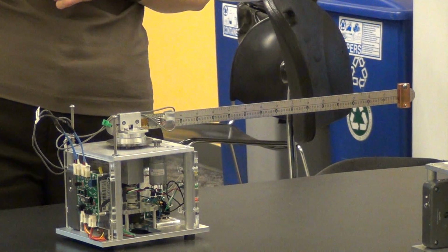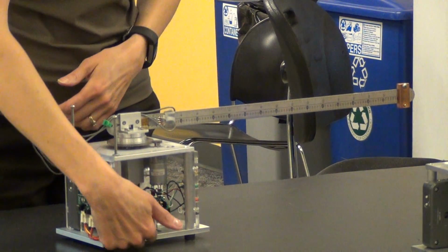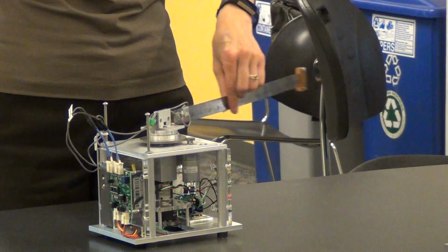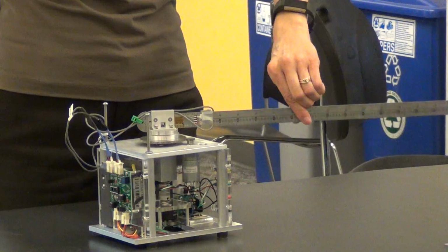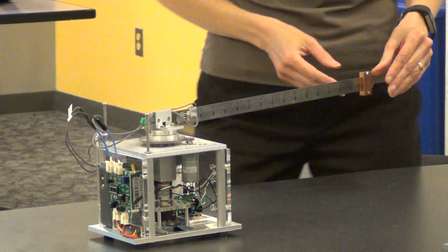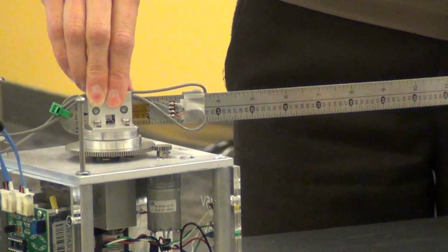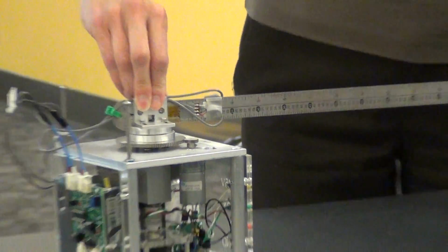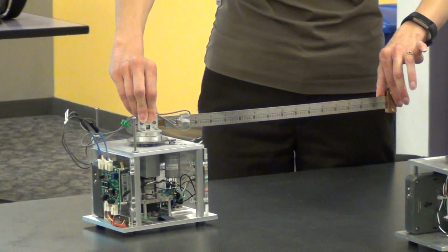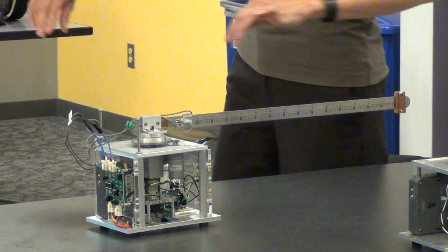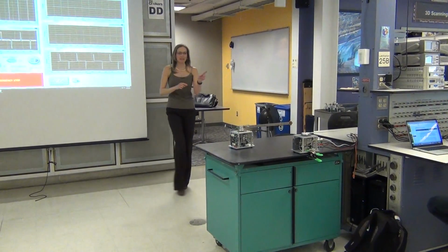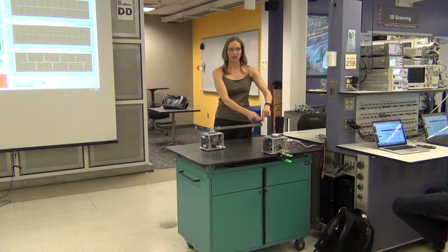Now we have 2 sensor feedbacks. We still have the same potentiometer for angle of the hub. That's our hub angle, so that's our pointing position. But we also now have a sensor to tell us how much the tip is deflecting, because I do not want this tip to bend too much or my solar panel is going to break. So the tip deflection is read out here in meters. That's how many meters this tip has deflected in this perpendicular direction.